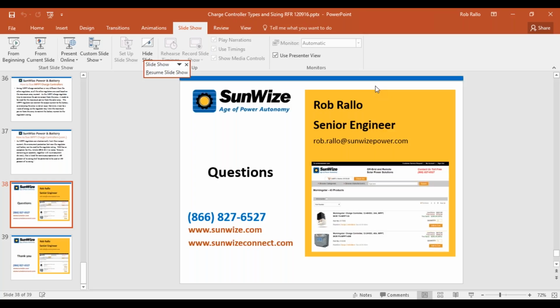Again, if you've got an array that's away from the battery, you may want to run that array at a higher voltage and step it down so you have less output cable, so you can save some money there. But if you're just trying to do it for extra power production, it's most likely going to be cheaper to just go to a slightly bigger module or add another one depending upon how big your system is. Generally, there are going to be some exceptions to that, so that's one of those that might be application specific, and you may want to talk to your salesperson or whoever you're working with regarding your system sizing for that.